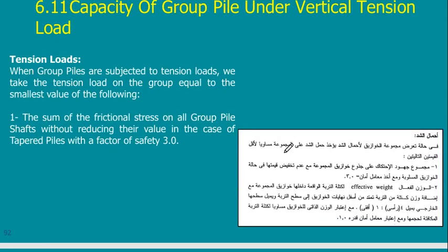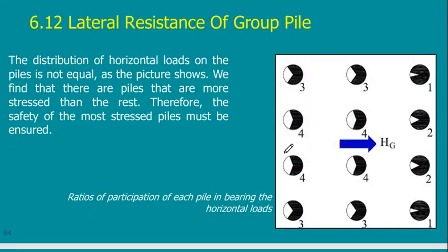This is just a quick note. Here also another thing, the lateral capacity of the pile. You should know that when I have a lateral load, pile 1 here and pile 1 here are always the major carrying piles, because they are subjected to bearing on this soil here and friction on this soil here, bearing on this soil here, friction on this soil here. So this is the maximum.